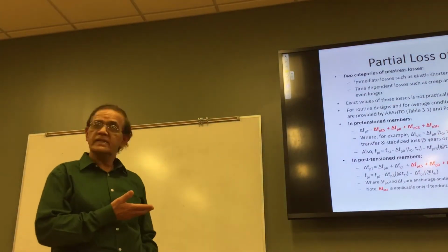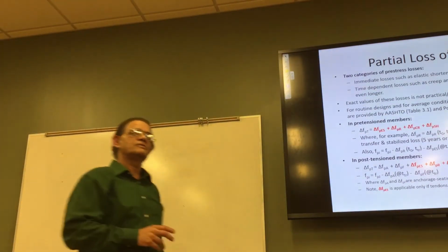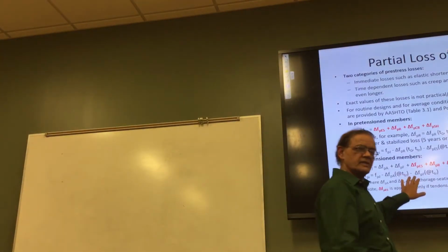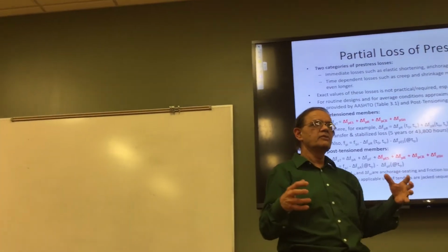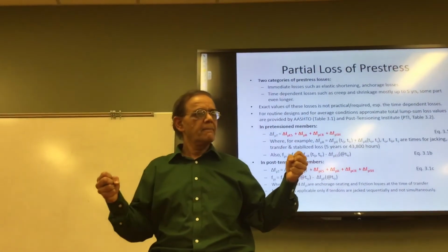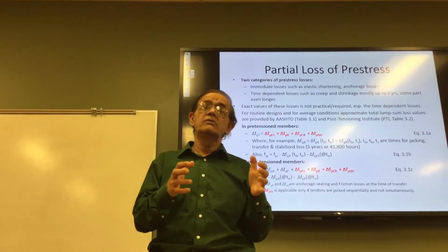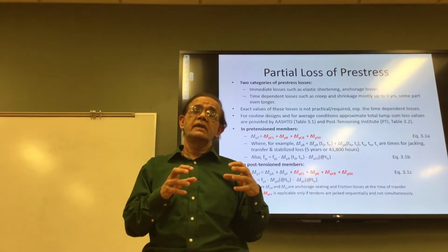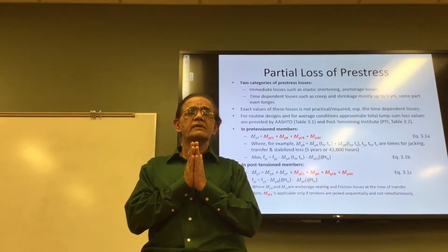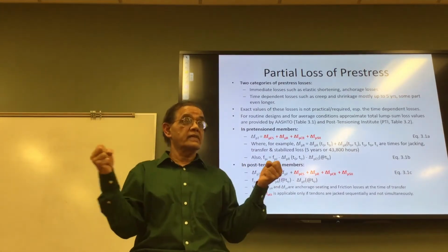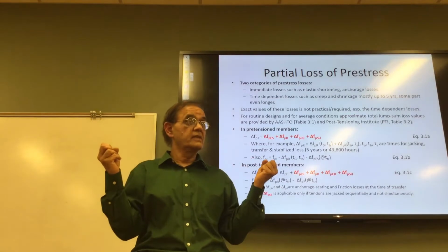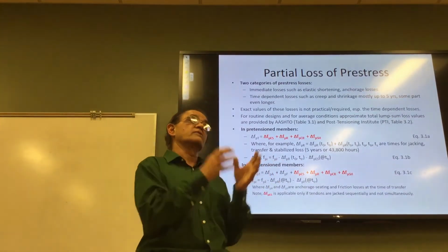And then these are exactly the same phenomena, which is elastic shortening. Just to be sure, like last time we talked about this, elastic shortening. If you pull and you allow it to go into the wedges, and you are doing it all together in one stretch, all wires and all strands, then there is no loss because they're going together.